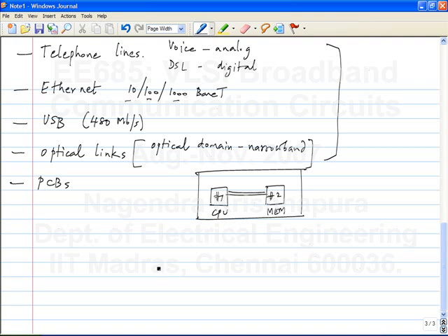So this is one example, and there are what are known as backplanes. Backplane is nothing but a large PCB, which holds a large number of small PCBs. They are known as line cards. So finally, all of your, let's say, Ethernet traffic goes through some switches and so on. So you can see some of these backplanes in those large switches. So you have many links which are put together, and then you have to connect between various links, and you will have backplanes. So it's nothing but a large PCB with PCB traces up to 1 meter.